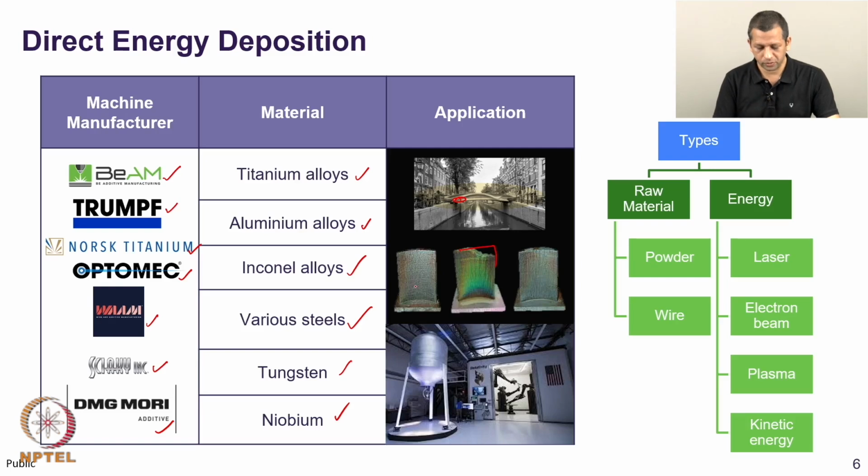It can also be used for making the turbine blades from scratch, like the other technologies are used. And since it is a faster technology, the overall throughput using DED is much faster. It can also be used for making large complicated structures, because the degrees of freedom available using DED are many more. Thus, hollow cylinders or pressure vessels can also be made using this.